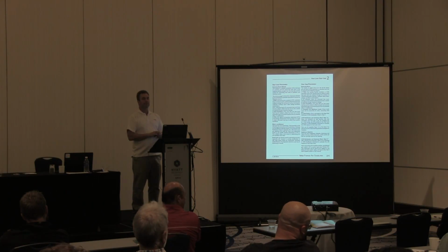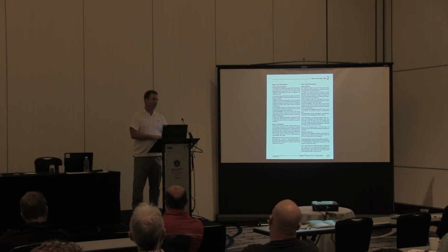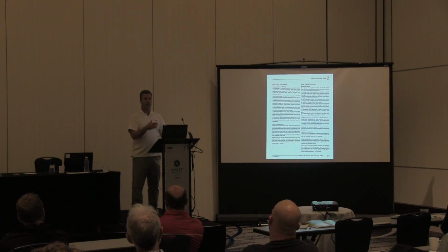If you do a heat loss, in your experience, how close do you come to what you ultimately know you need? The way I do the heat loss, it's under 10% different from the room by room. Wow. But I've been doing this a long time, so my experience tells me things when I put the information in. Because it's no different than anything else: computers aren't usually the mistake. If you put garbage into a computer, garbage is going to come back out. So you've got to make sure that you put the right information into the sheets, whether you're doing it longhand or using a computer program.